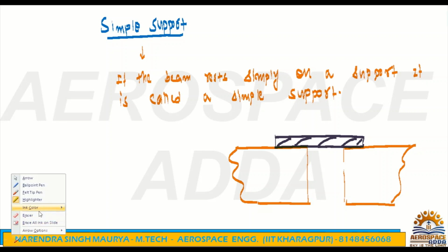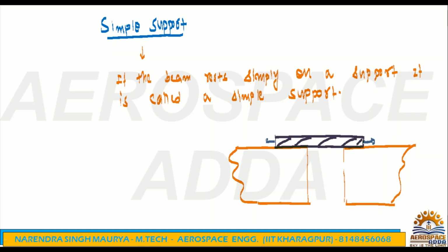Now, a very important point you need to remember: for the simple support, the reaction at the support is exactly at right angles to the support, and the beam is free to move. This beam is free to move in this direction, as well as in this direction also. It can move easily, no problem. And where is the reaction?